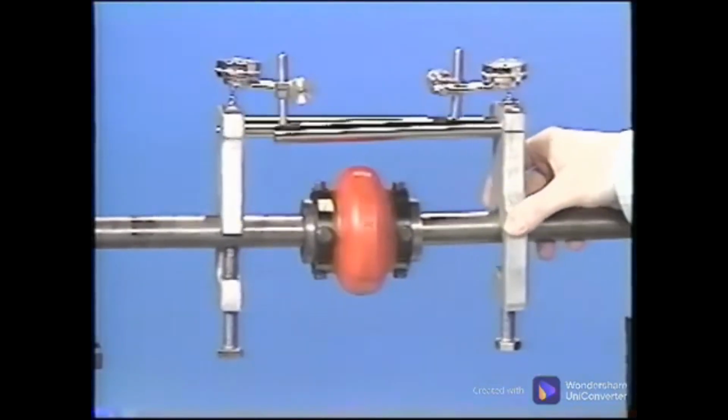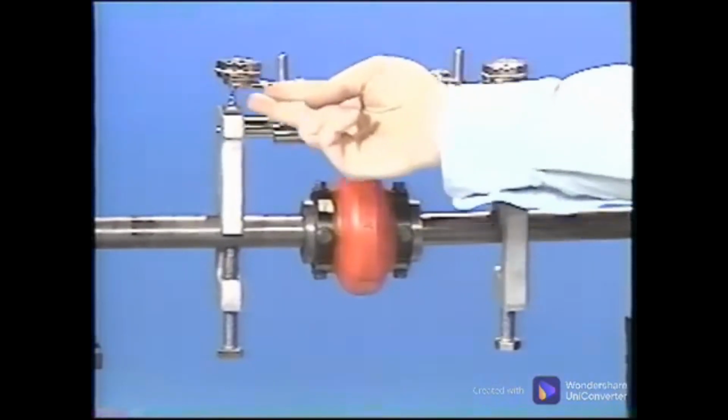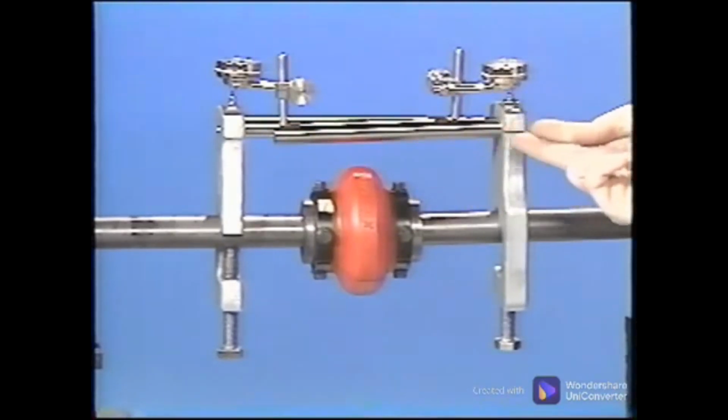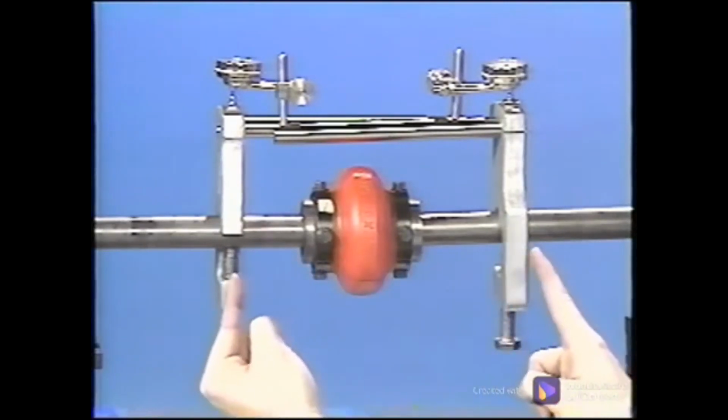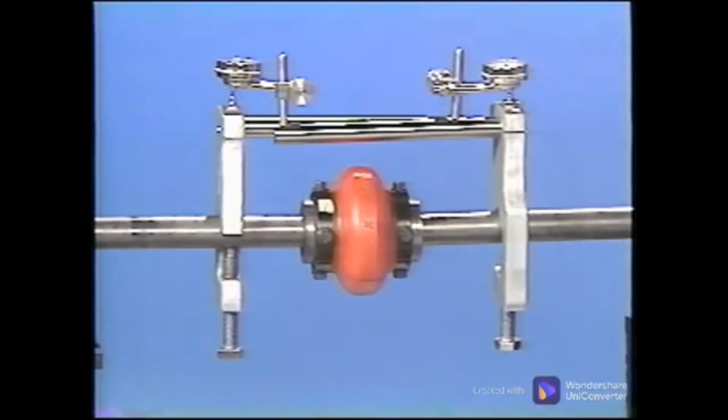A dial indicator is mounted on each shaft, and the dial is actually measuring across the coupling to record the relative movement of the opposite shaft. These measurements are then mathematically or graphically projected to the machinery feet, where corrections are then calculated for adjustments and shimming the feet. This method can be used for longer spans than the face rim method, and because the shafts turn together, it is independent of coupling runout.